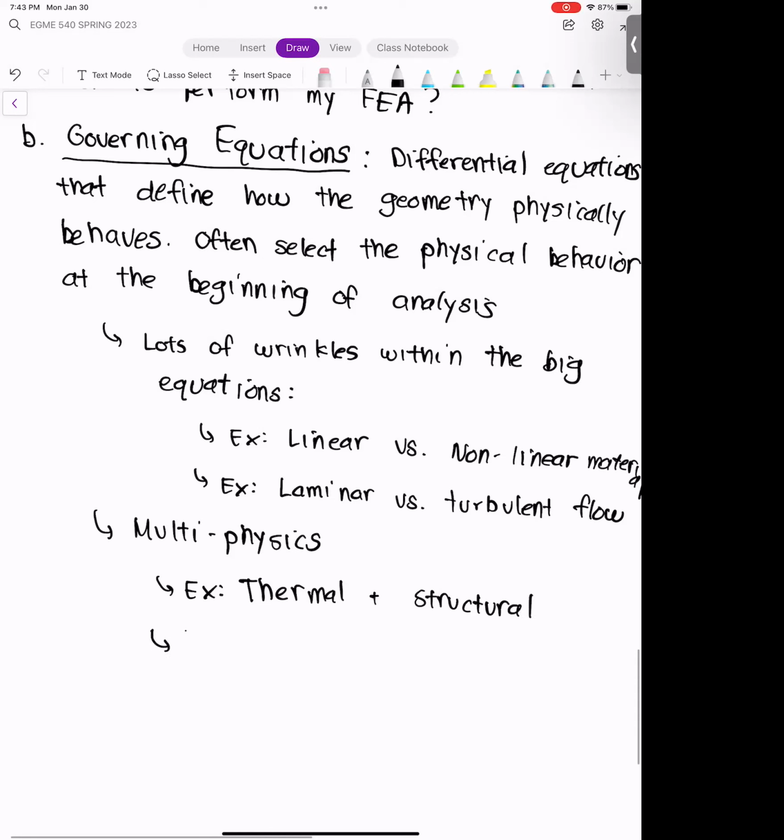Dr. Chang, can you please repeat your last sentence? Yeah, what I was saying is that people combine thermal analysis with other types of analysis because a lot of material properties depend on temperature. Structures is one like that as well. A lot of materials, their density changes based on their temperature, and their stiffness depends on temperature. So if you have a situation where the temperature is going to be changing in your geometry, you're going to want to solve both structures and thermal. I see. Thank you, sir.